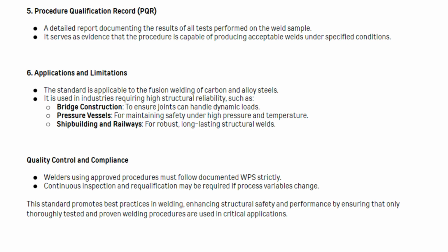5. Procedure Qualification Record, PQR. A detailed report documenting the results of all tests performed on the weld sample. It serves as evidence that the procedure is capable of producing acceptable welds under specified conditions.